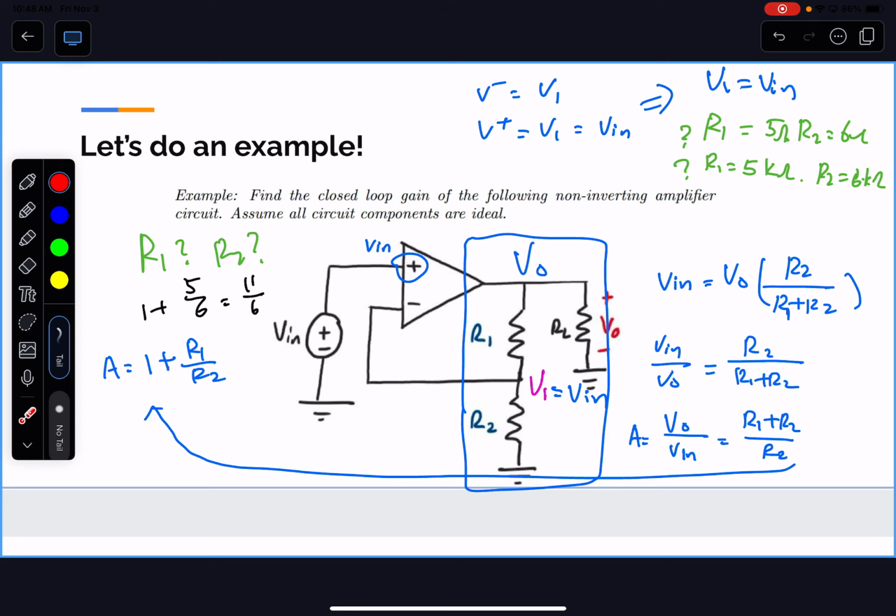Normally your cell phone charger is like 0.5 or 2 amps. It doesn't even go over that. So just by doing that, the biggest problem is not even the fact that the circuit is safer or not. Even if your circuit is beefy enough to take it, the biggest problem is you only have a finite amount of current coming out of here. You're gonna split off the majority of it going through it just to get you that control. What about the other components you're trying to drive?